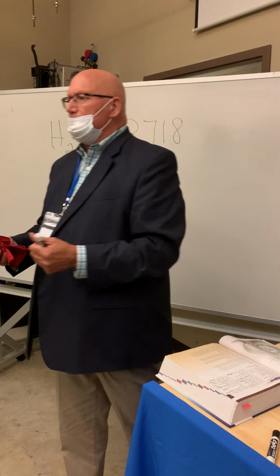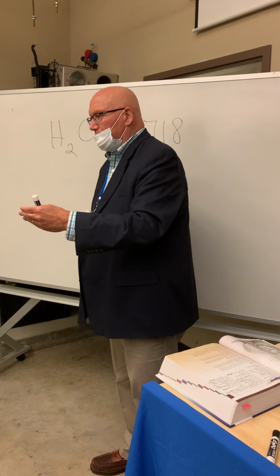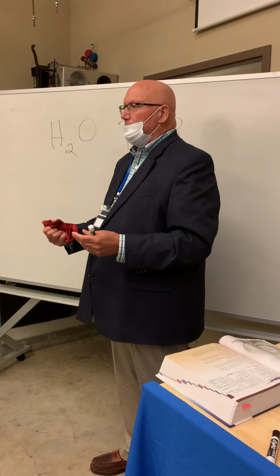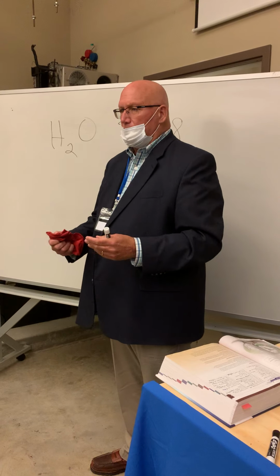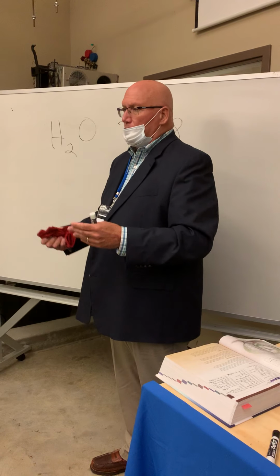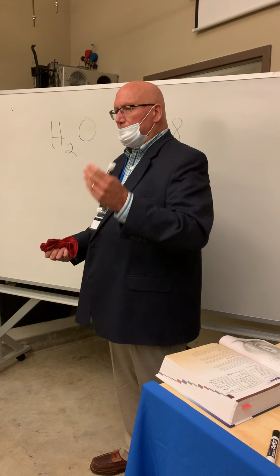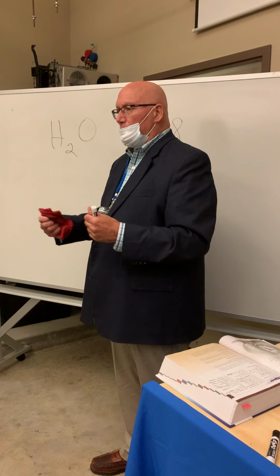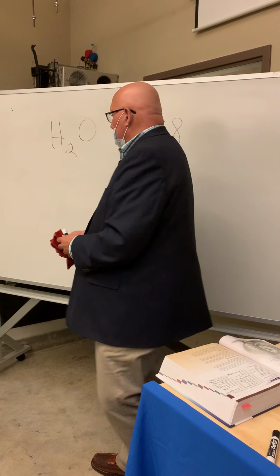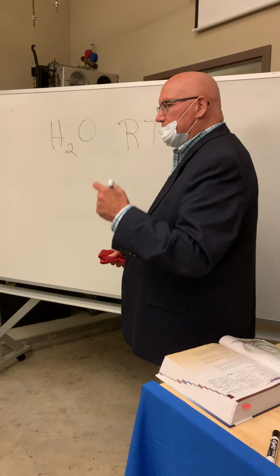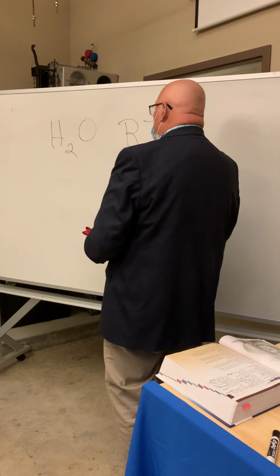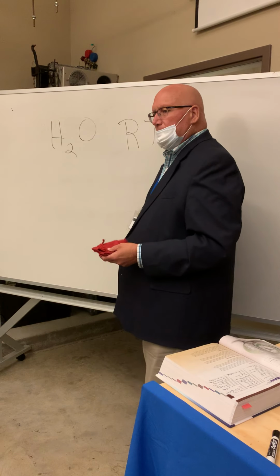We use water as what's called a secondary refrigerant inside big buildings in Manhattan. We don't have a ton of refrigerant vapor, refrigerant liquid flowing throughout that entire building, those skyscrapers, but we have treated water. So we cool the water, or we heat the water by absorbing the heat in the room, and then we remove the heat from that water. So I'm bringing this up because I want to get a base level for our science piece here. So we're going to look at this refrigerant for just a moment.